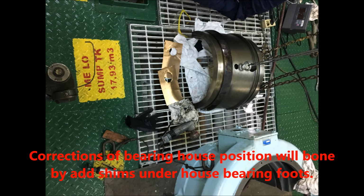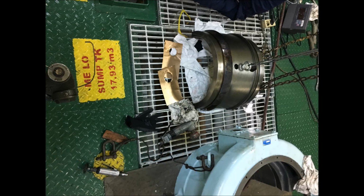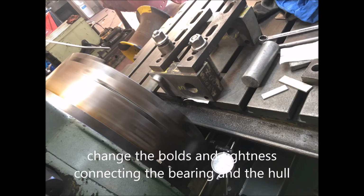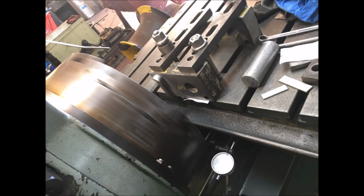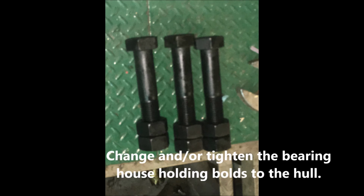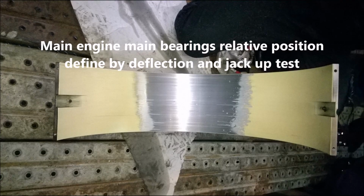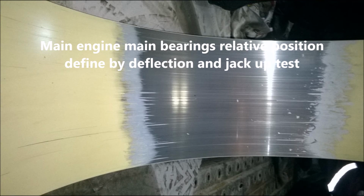Corrections of the bearing house position will be done by adding shims under the bearing house foots, reducing the bearing house pad's height or casting new chock fast, and changing the bearing house holding bolts to the hull. The main engine main bearings' relative position is defined by deflection and jack-up test.